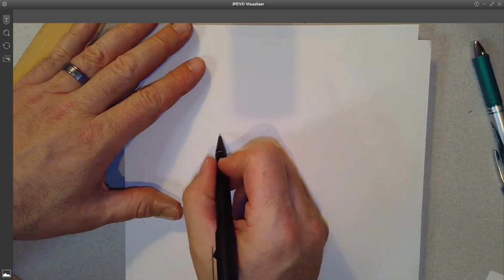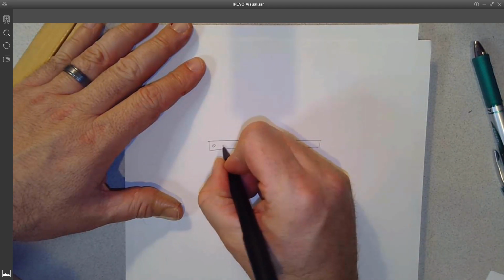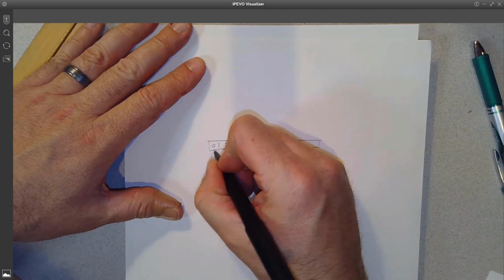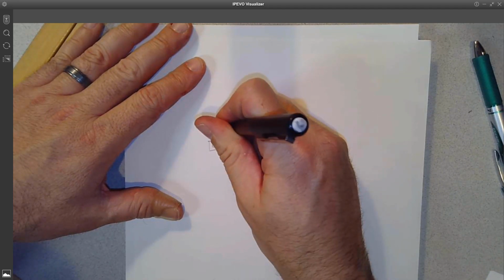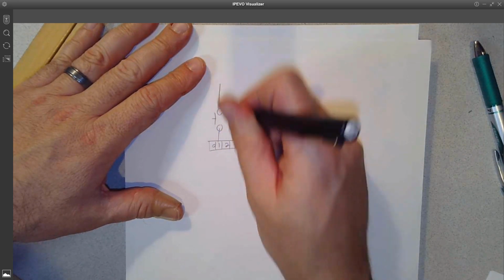The first main half is creating a schematic for how you're going to connect your inputs and your outputs to your PLC. Real similar to how we did the last assignment. Just show me the terminal numbers on the PLC. It can be basically a black box. Let's grab a piece of paper. Show me the input, 0, 1, 2, 3. Break those up and then show me the devices connected to them. Say maybe I had a push button on this one.